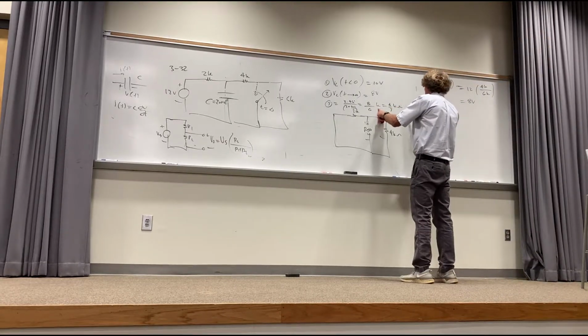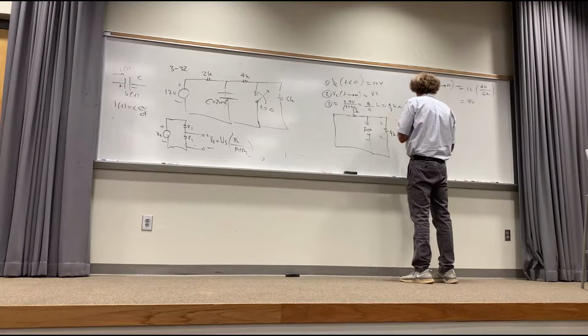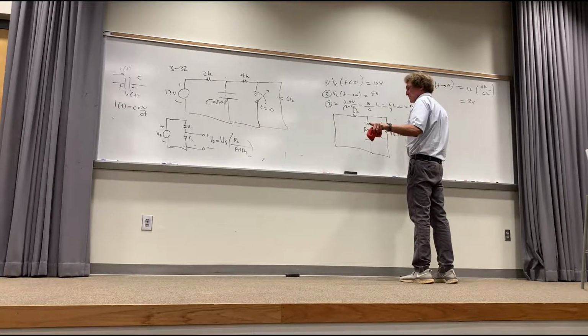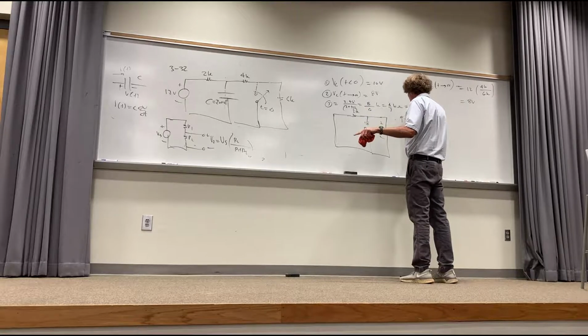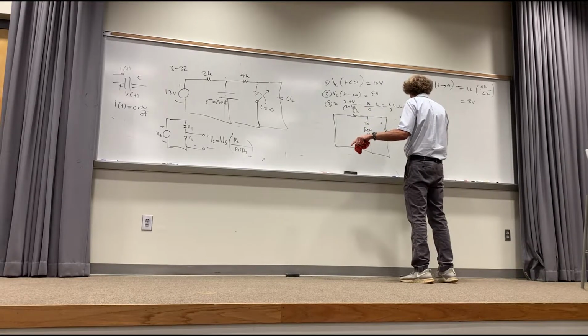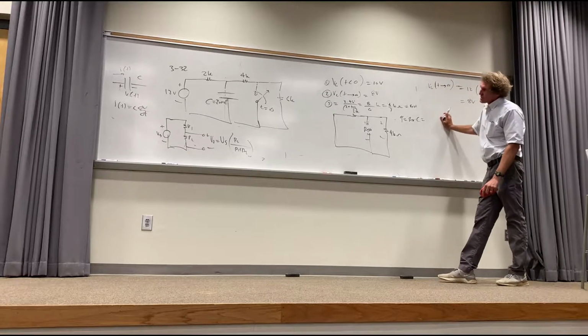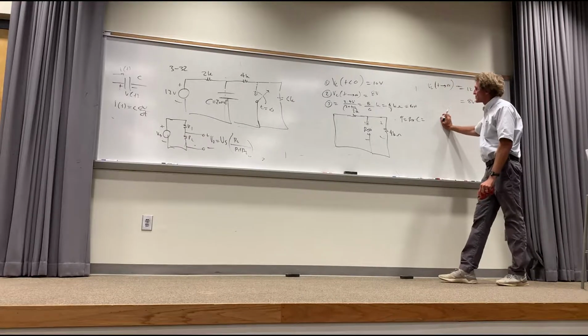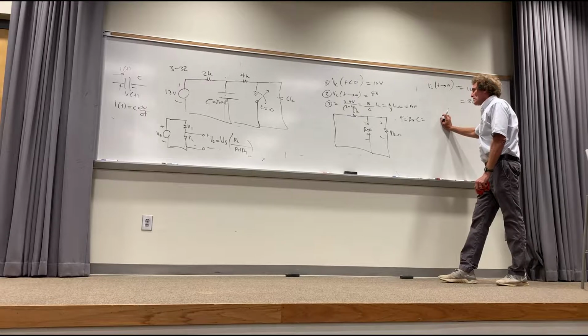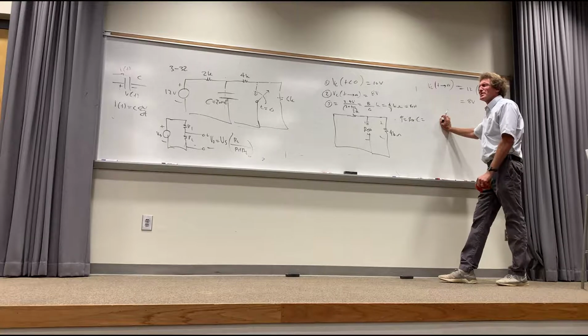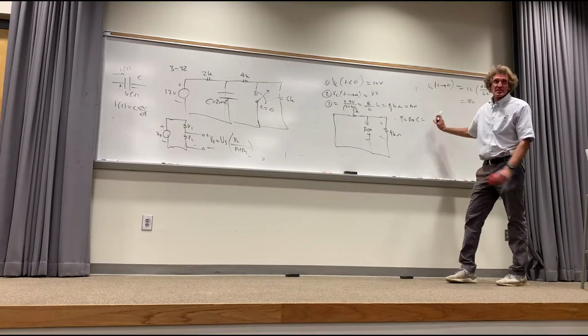After I get R Thevenin, there's one other thing that follows suit for an RC problem. What is that? Tau. And tau is R Thevenin times C, right? So it's 4/3 of a K times 2 times 10 to the minus 4th. That's going to be, I think, 0.266, is that right?